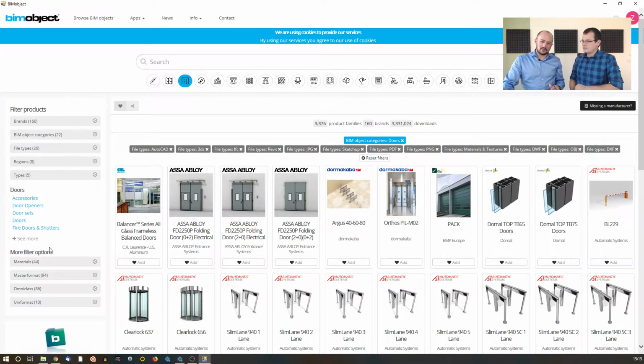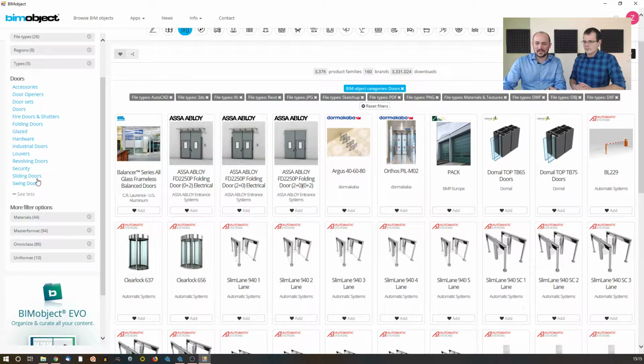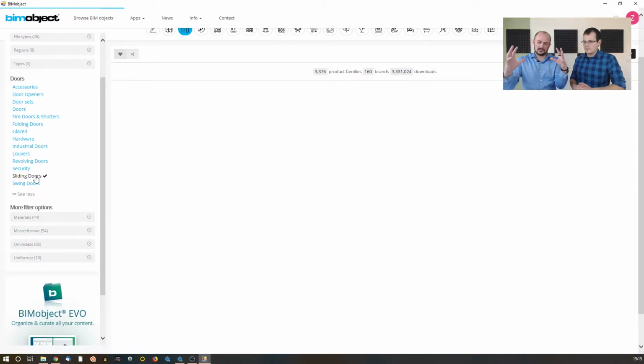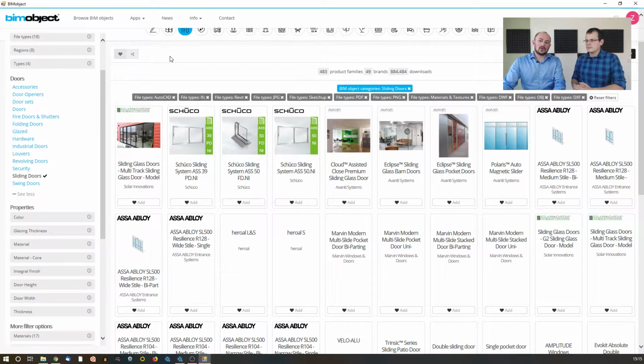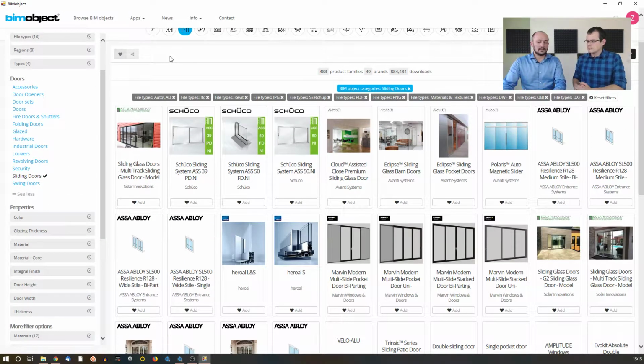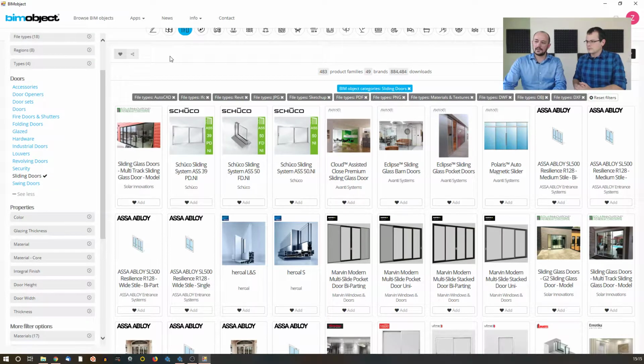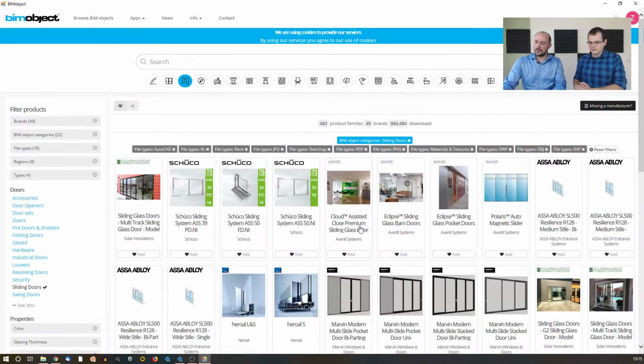And then also there are filters at the left-hand side, just as, if you're familiar with the non-BIM library, the warehouse, there's also a filter there, like a search field and so on. This is quite similar. So you just go and find a category, filter it if you want. I think I tried to find this sliding door category, so I'm just narrowing my search. Also, here, there's this BIM board, which is like the favorites list. We actually already stored some of our favorites, but let's just go with these here.